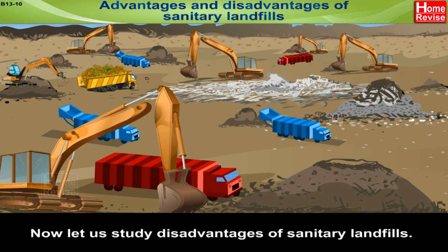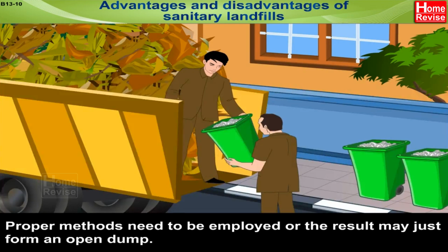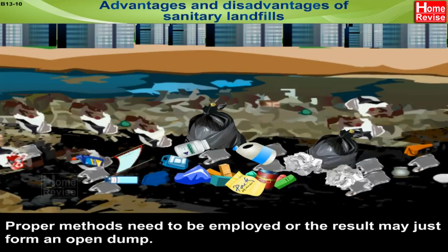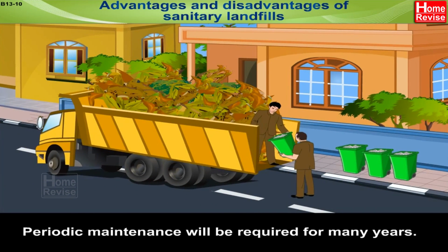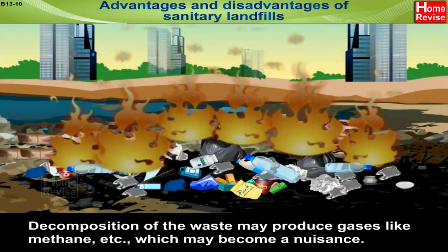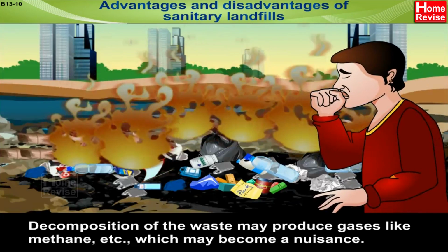Now let us study disadvantages of sanitary landfills. In highly populated areas, suitable land may not be available and transport to a suitable place will add to the expense. Proper methods need to be employed or the result may just form an open dump, which is dangerous. Periodic maintenance will be required for many years. Decomposition of waste may produce gases like methane, etc., which may become a nuisance.